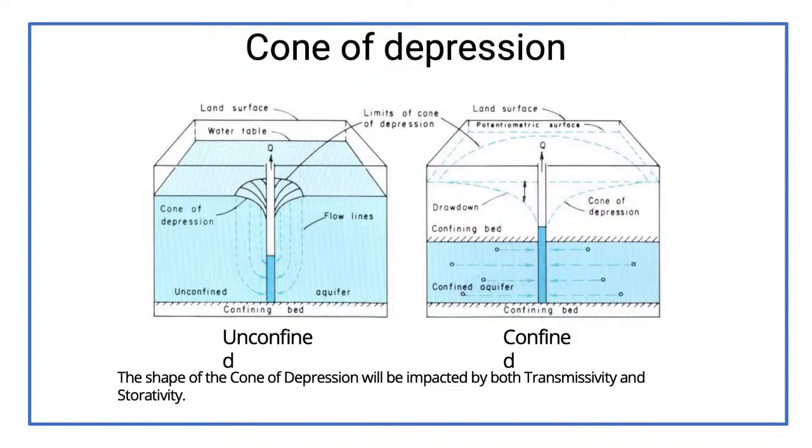The water is flowing to the well under gravity, and as that cone of depression increases, as we pull more water out of the well faster than it can flow in, you're going to build a hole in the aquifer and water is going to be flowing in there. We can measure that, and it's going to have a certain velocity that comes in. That's going to affect our well design. But if a cone of depression expands out far enough, we can create interference with neighboring wells, and we've got to be able to get a handle on that.